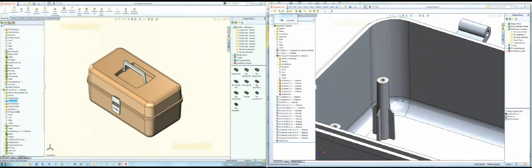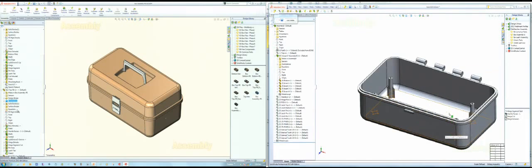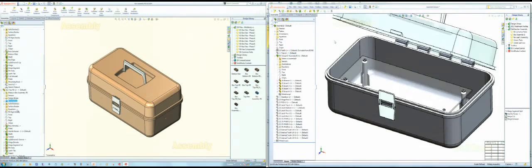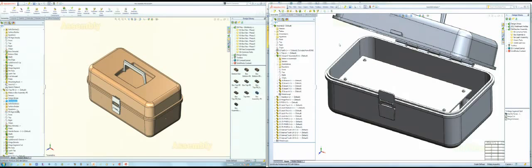Okay, and then the last thing I did is kind of optional, and I've used this successfully through a fair number of projects. I actually brought in the master model. In other words, that multi-body file is just hanging around out on the drive, right? We have to keep that around. We cannot get rid of that or this assembly will just fall apart. That is the parent to everything, so we have to keep it around. Well, where's a convenient place to put it so you'll always know where it is? Why don't we just bring it into the assembly? This assembly that we just created.